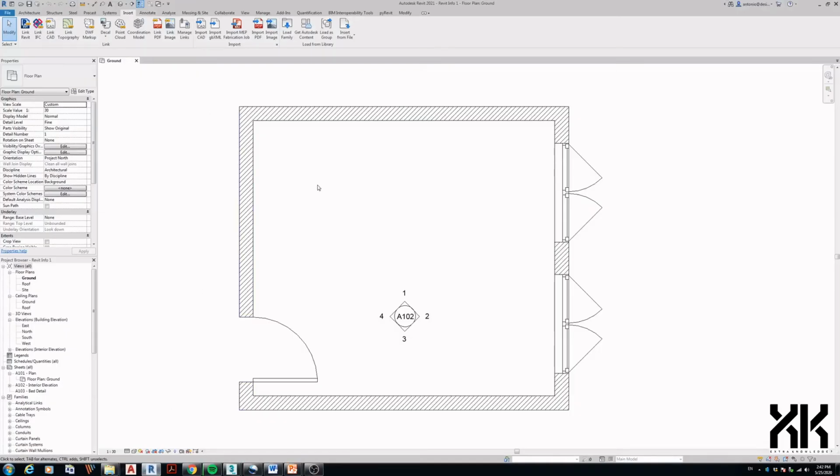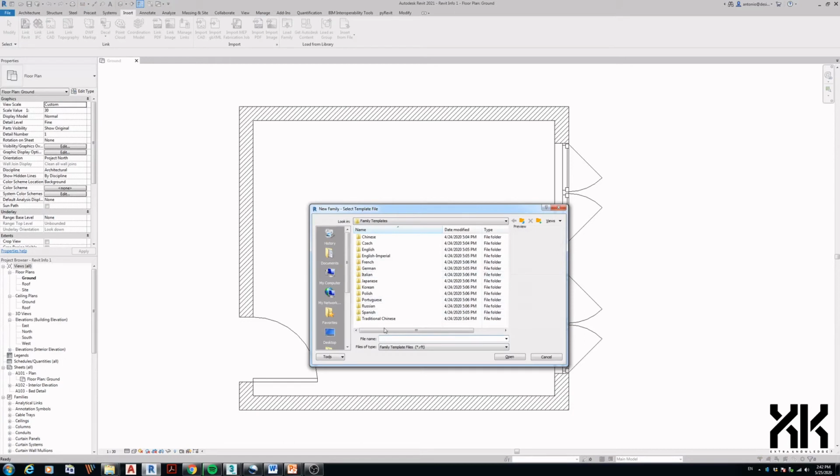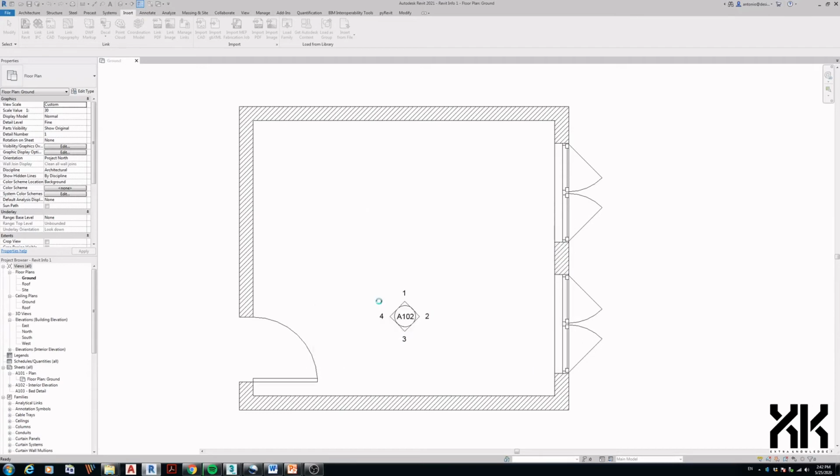In Revit, let's assign our models in detail level. This time, instead of inserting our DXF file directly in the drawing area, we will create a furniture family since our model is side tables and lampshades. Click File, Family, select the English folder, and select Metric Furniture Family Template.